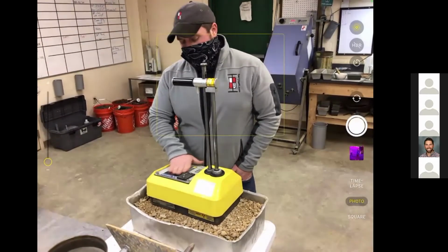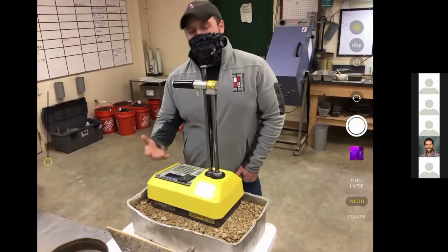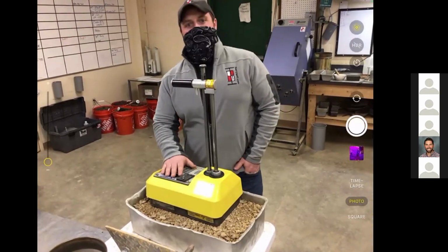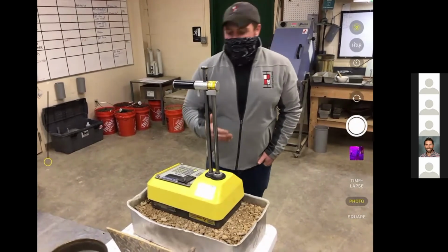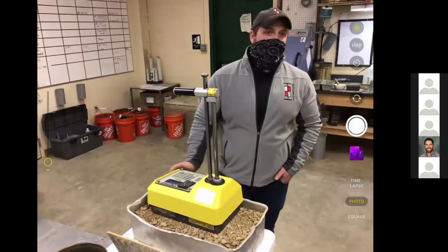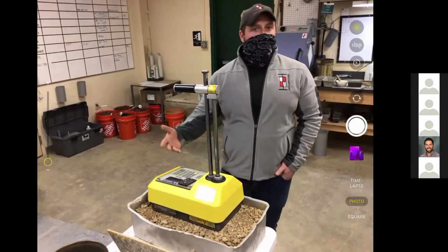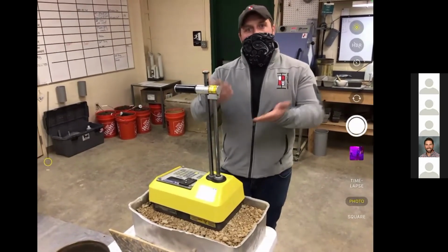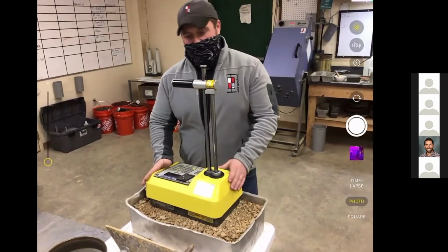The other good thing that it does is if you're unsure about moisture contents within that soil, this gives you a good idea. So it helps us help the contractor, help our clients out in the field by saying, hey, your moisture content's way too low in the summertime. So what we're gonna have to do is wet the soil up a little bit, mix it in, recompact it, and then we'll test it again. Once we get that moisture content elevated slightly, usually we can get within that range to get the proper compaction.